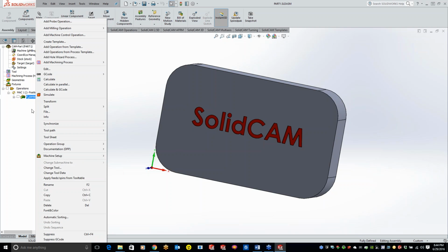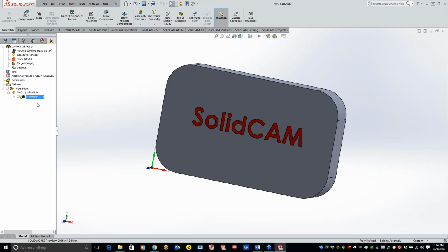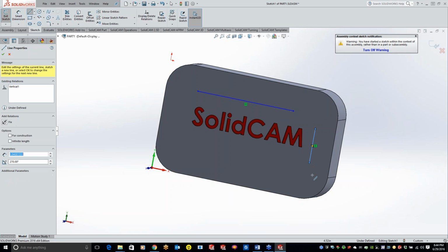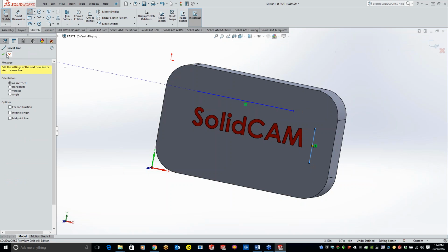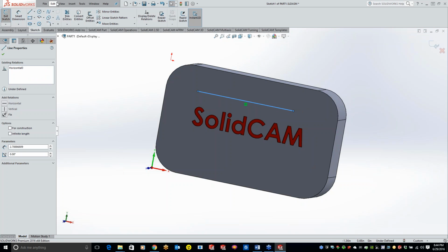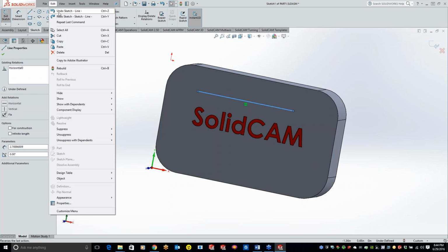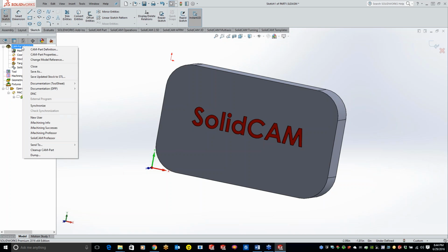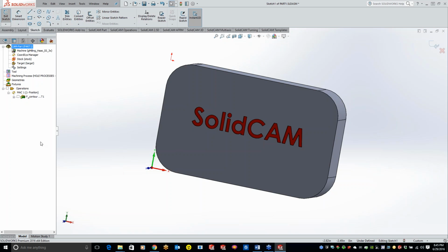Yeah, there is. If you do a toolpath over here and you didn't want it, there is no undo button. But let's say you did a sketch. You draw the sketch, in terms of SolidWorks functionality, you can come over to your file, hit Edit, and then hit Undo Sketch, and it will undo the sketching properties. There is no undo inside SolidCAM here, so we can't just right click and undo. I'm not sure why they don't have it in there. I can definitely find out for everybody, but hopefully that answers your question there, Ronnie.